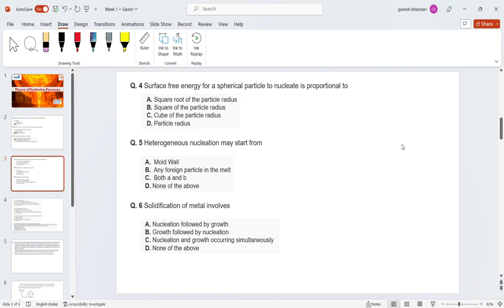And second, the solidification behavior completely changes, because the lead-tin alloy eutectic point comes at around 184, while if intermetallics are present, then your melting point changes to around 400 degrees centigrade. So your complete chemistry will change. Your soldering application will be completely destroyed. That's why the effect of pure and alloying was taught. So go through it, and then again go through those questions and think about what the MCQs are.